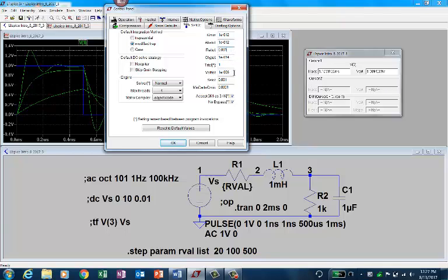Then you have the voltage tolerance and the current tolerance. These are the main ones: the absolute tolerance of all voltage and current, the relative tolerance of current, and the voltage tolerance. These are the three more important things. This is all of them.